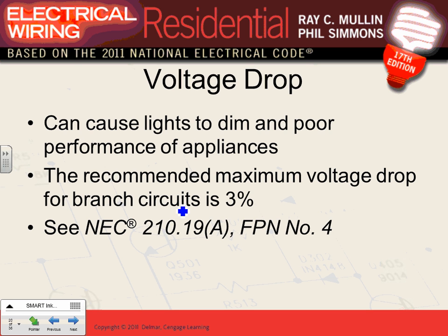Voltage drop. We'll talk about voltage drop, guys. I have a couple of examples. Voltage drop in the NEC code book is actually, believe it or not, an informational note. So it's a recommendation, not a must, even though a lot of us take it as a must. There are a couple of examples of the problem with voltage drop. Especially in residential it's not a big deal, but in commercial it's a big deal.